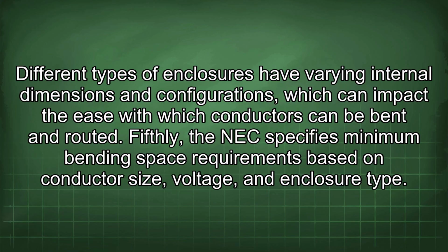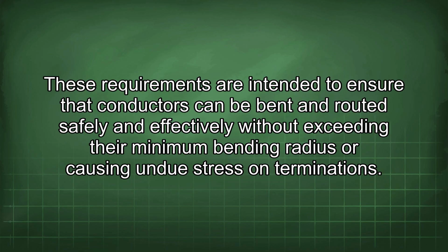Fifthly, the NEC specifies minimum bending space requirements based on conductor size, voltage, and enclosure type. These requirements are intended to ensure that conductors can be bent and routed safely and effectively without exceeding their minimum bending radius or causing undue stress on terminations.